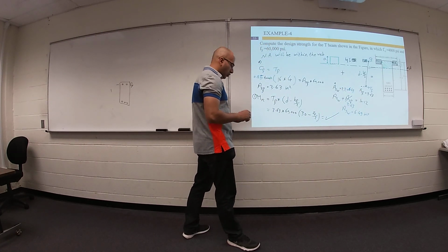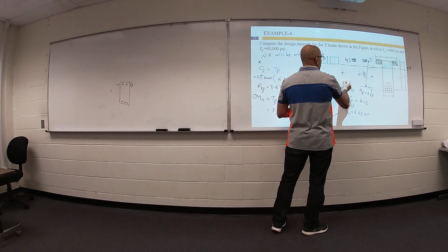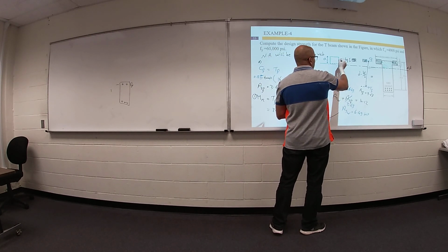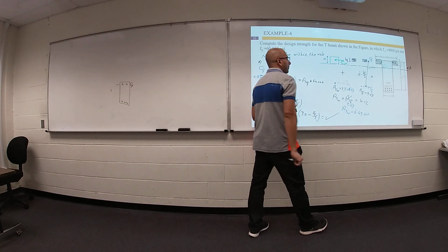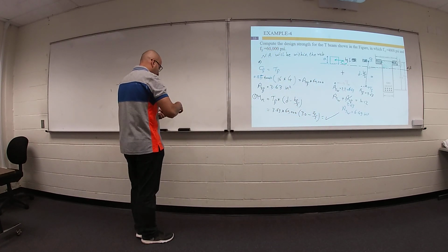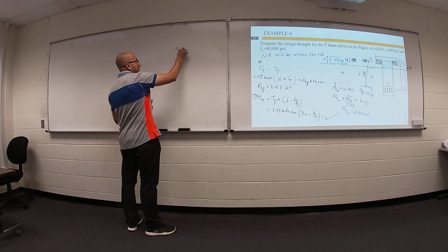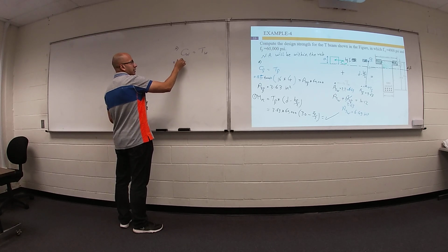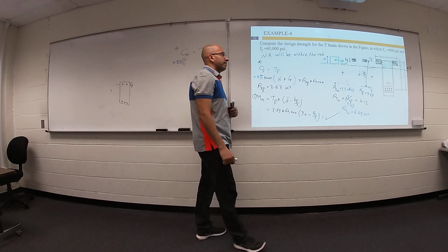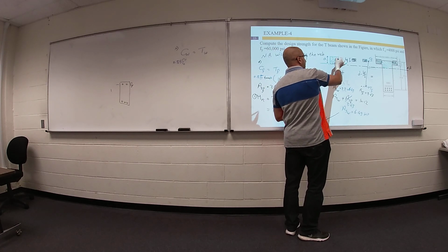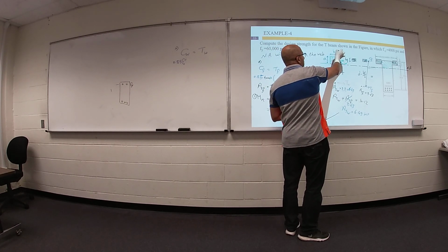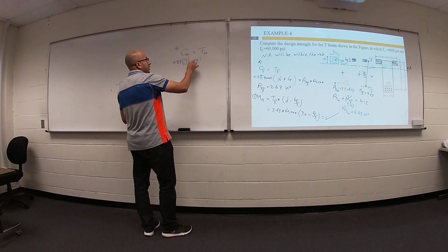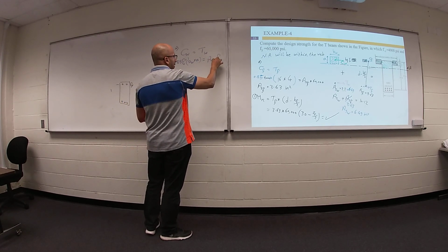Go ahead, do the same. We have here tensile force called T web. We have a force here, compressive force called C web. For the second part, C web equals T web. So 0.85 f prime c times this area. This area equals b web times a. b web times a equals area steel web times f yield.